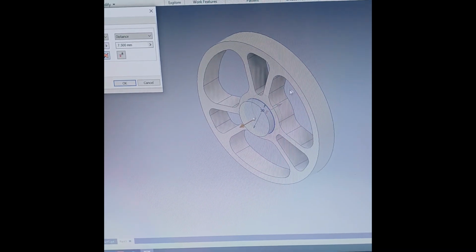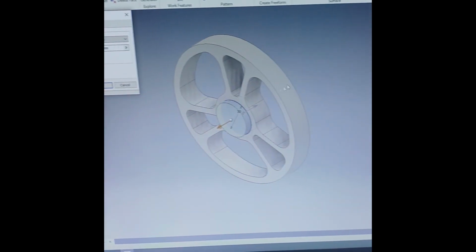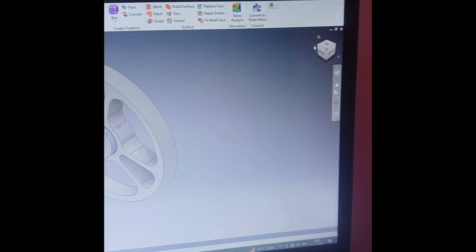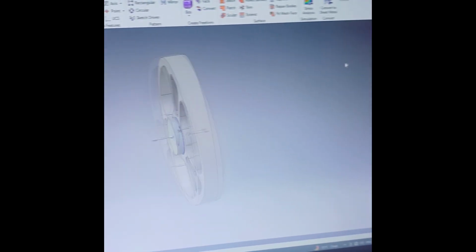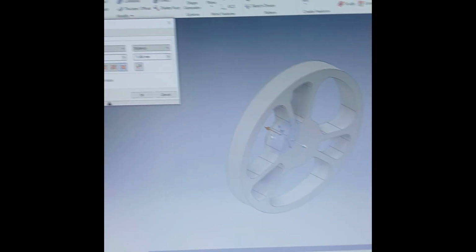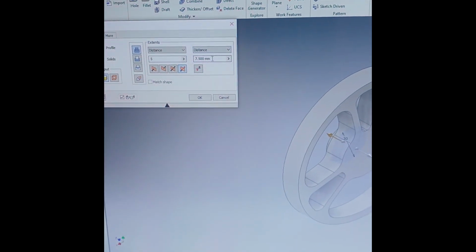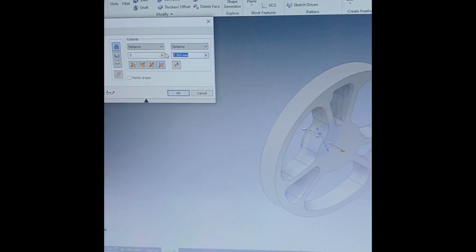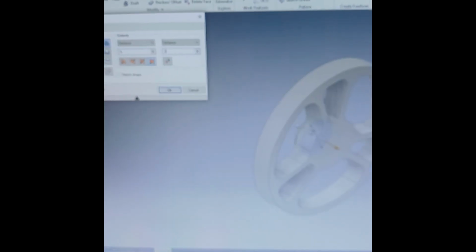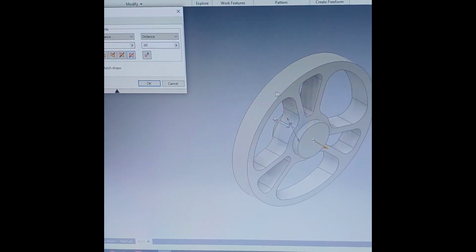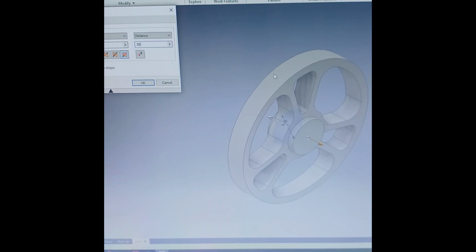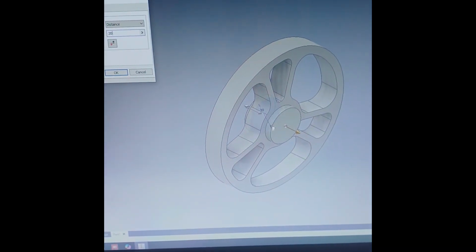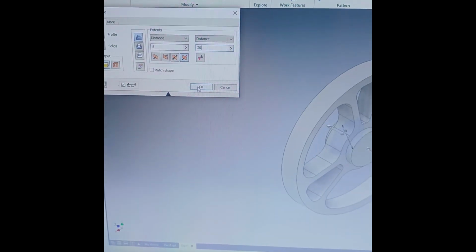Now it will travel up to the next side and come out by 5 mm. So I'll rotate the profile once again. So this is the back side. Now here it is taking 7.5. I'll change it to 20 mm. Okay, so 15 mm will be this profile and the 5 mm will be the outer profile. And press OK.